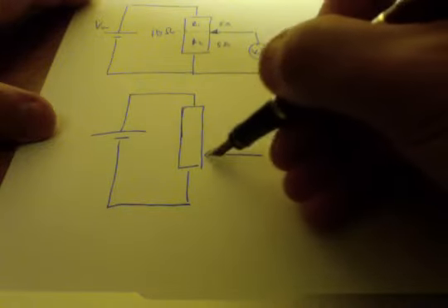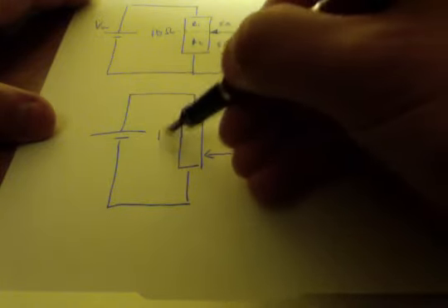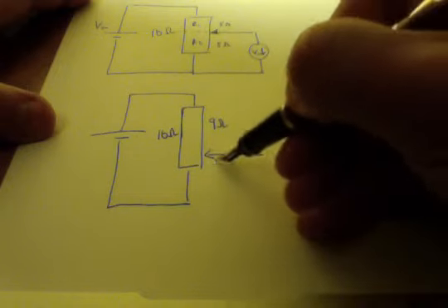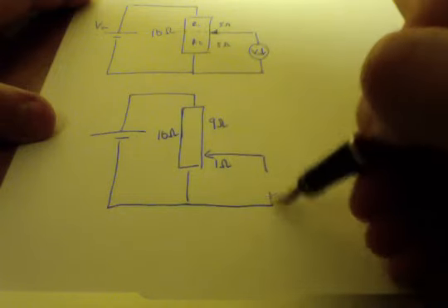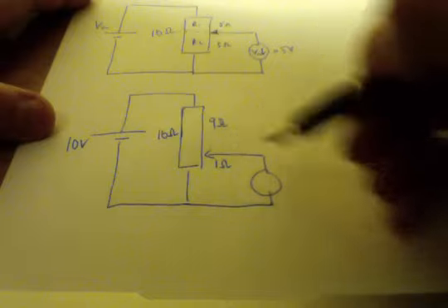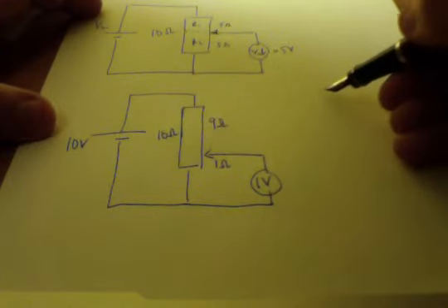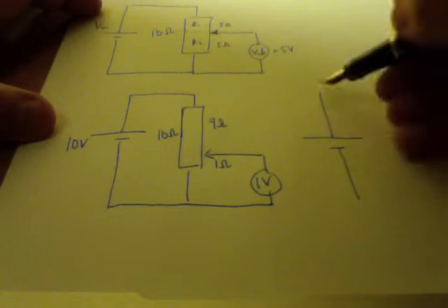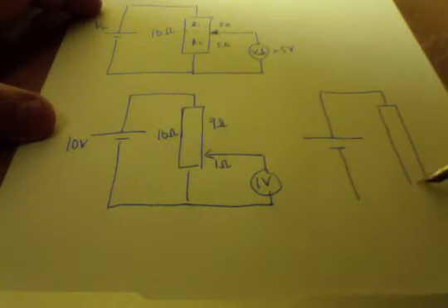However, you can very easily cut it at any point, let's say down here, where of our 10 ohms you might have 9 at the top and 1 at the bottom, which means that, whereas here you'd get 5 volts out because it's an even share, here, of the 10 volts, you've got 9 up there, 1 down here, you've got 1 volt there. Or alternatively, you could have the reverse, and you could be working right to the top, where you have 1 ohm at the top and 9 ohms at the bottom, which means that you would get 9 volts.